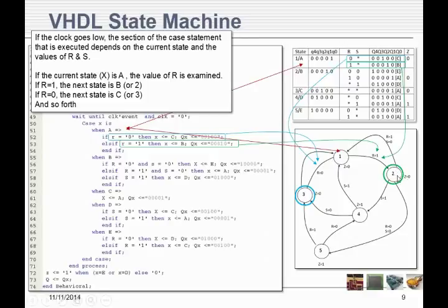So I've got 3 transitions coming out of state B, and I better have 3 here. Only one way to get into state B. So here it shows that if R and S are both 0, then X is going to be in state E, which is down here, state 5, and Z is going to be a 1. And that all takes place in here.